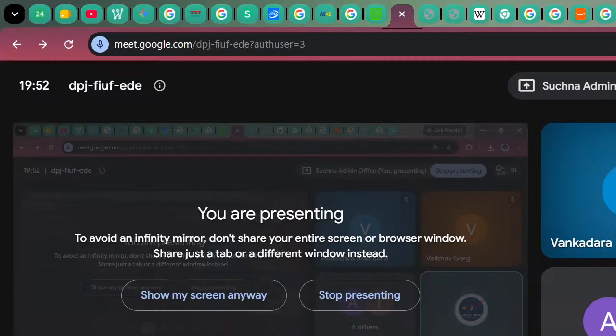Cobalt is also used. Cobalt is used in gold fingers. In gold fingers we use a small percentage of cobalt, around 5 to 10%. Why is cobalt used in gold fingers? Because cobalt increases rigidity. That's why 5 to 10% of cobalt is used in gold fingers.